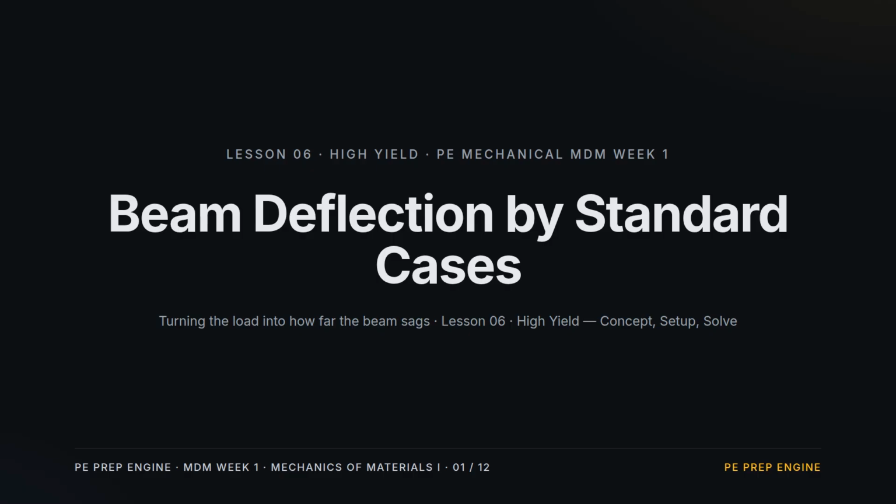3 one-line ideas. Deflection comes from a table. The deflection scales with the load over the flexural rigidity EI, and the span exponent and the coefficient are set by the support and the load type. Get those, and deflection problems are a lookup.